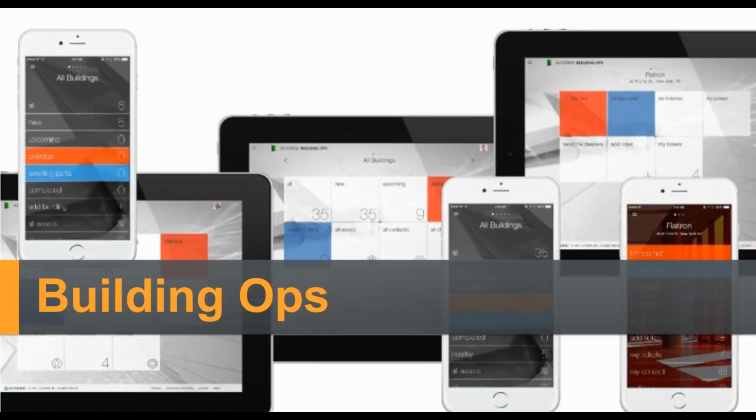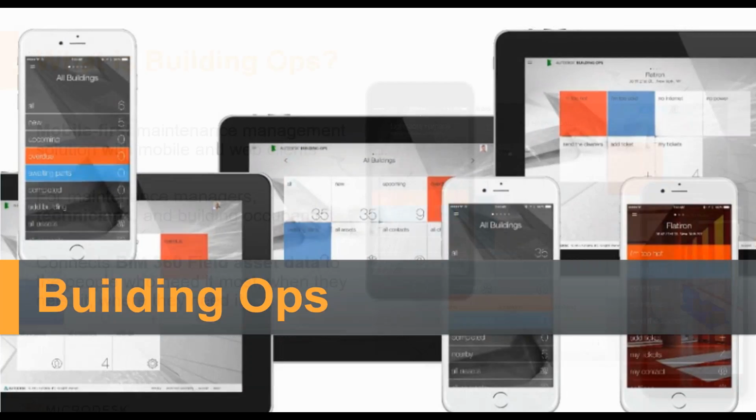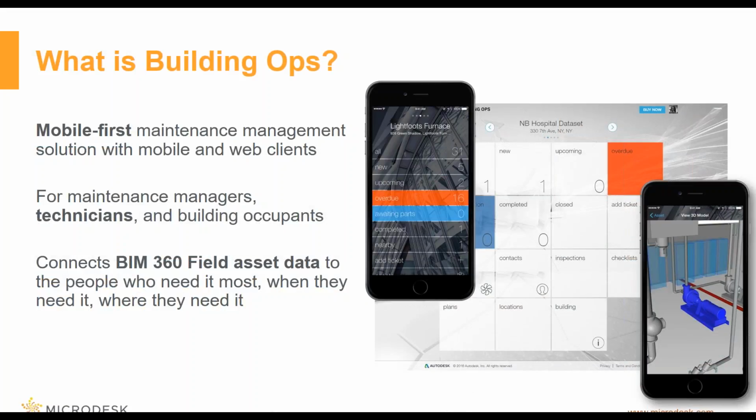Now, for one of the last ones here called Building Ops. Now, of the different BIM 360 services, this is probably the least known of them. And what BIM 360 Building Ops is, it's a mobile-first tool for building management. So typically what's going to happen is at the end of construction, the CM will submit to the owner, here's all the information, all the commissioning, and then the owner takes it from there and decides how they want to maintain or manage things. Now, what this does is I can actually pull that data from BIM 360 Field, or I can upload it otherwise, and I can actually maintain that.